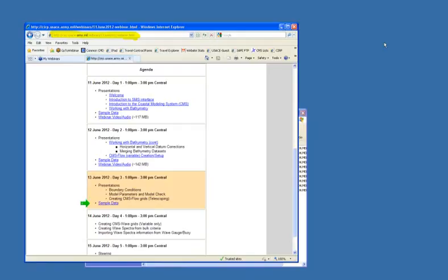So I've loaded that back in, dragged and dropped it to the interface, and you see here that I have a grid frame. I have the scatter points. I'm going to go into display options and show these a little bit different way. So under scatter, I'm turning off the points and turning on the contours and changing them to look at them by a color fill. And then I'm specifying a range just so that I see the same colors pretty much every time I come in and look at bathymetry.